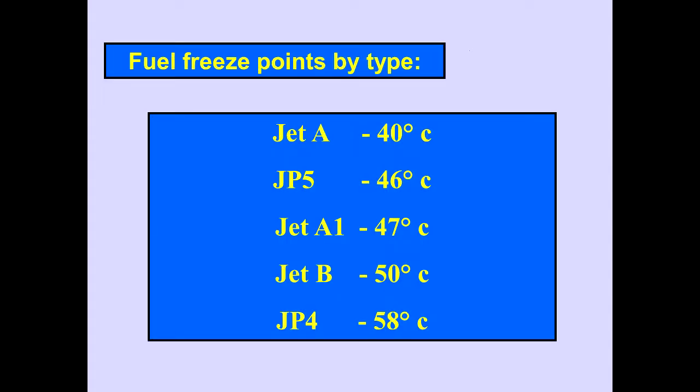The ICAS advisory message, fuel temperature low, is displayed when the fuel temperature is below minus 37 degrees centigrade. The fuel temperature display in ICAS changes to amber. Fuel temperature in flight must be maintained at least 3 degrees above the freeze point of the fuel minimum operating